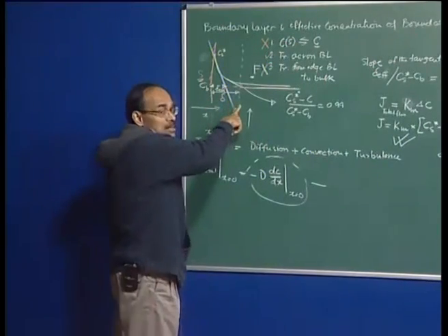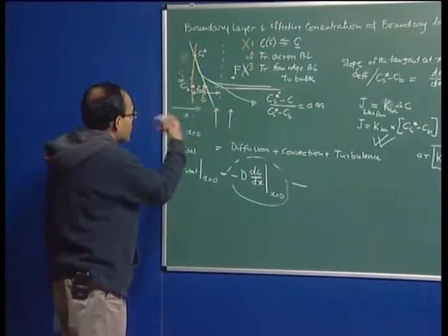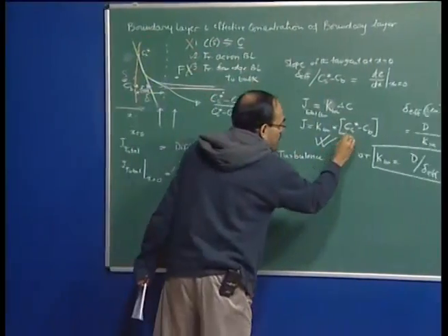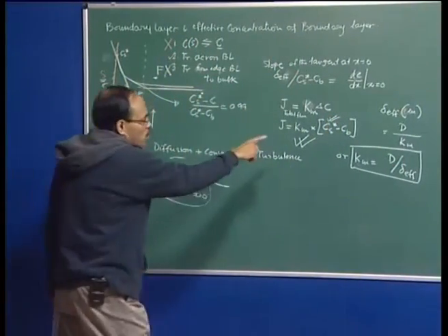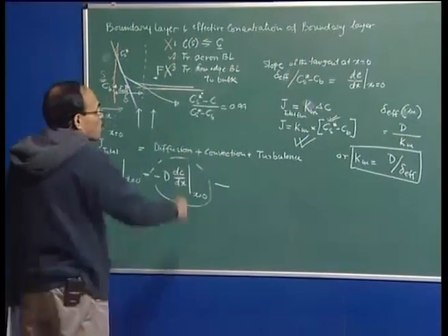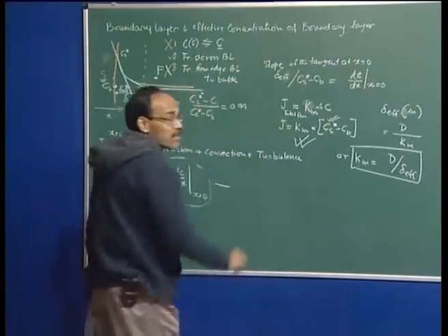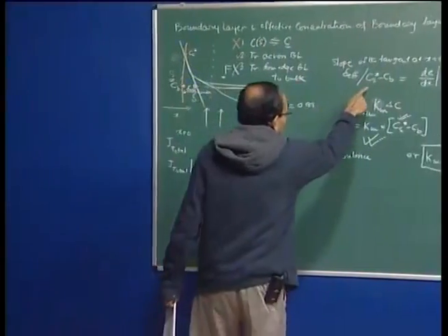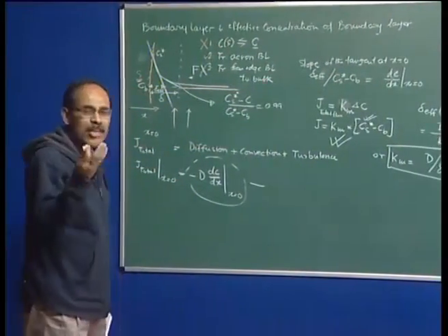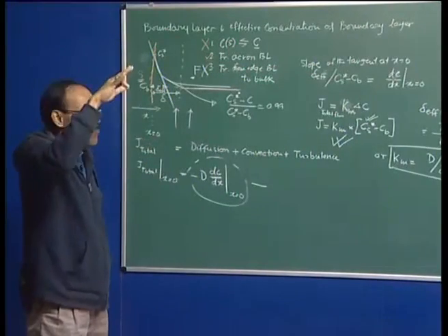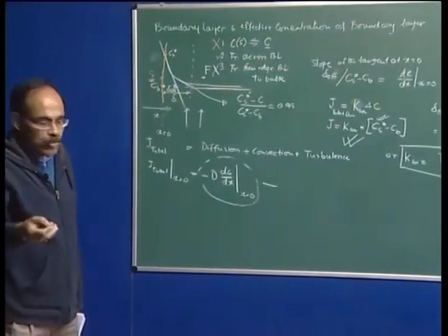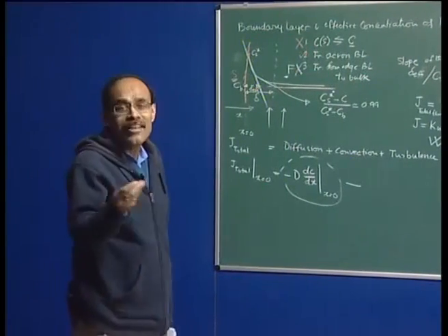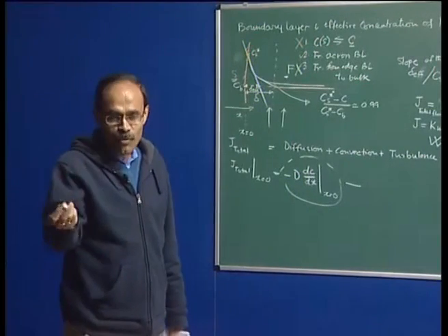At the temperature where I carry out the measurements, I can find out very easily what the saturation concentration level is, and therefore the surface concentration term can be known. So, the way the surface concentration, the interfacial concentration, during boundary layer mass transport is calculated is simply by the application of equilibrium concepts. In this case the saturation concentration is the surface concentration, and the bulk concentration of course can be taken to be 0, or it can be taken to change with time depending on whether the reactor size is much bigger than the dissolving species or not. For example, if I am talking of a 150 ton steel bath and I have added 2 lumps of ferroniobium, I can consider that the bulk concentration of ferroniobium is possibly 0.001 or 0.01 percent, and I can ignore it.